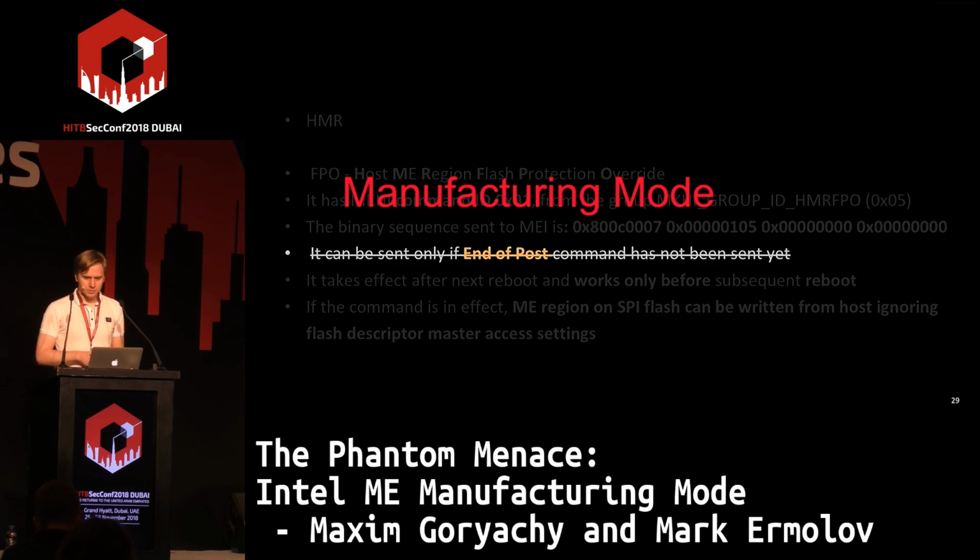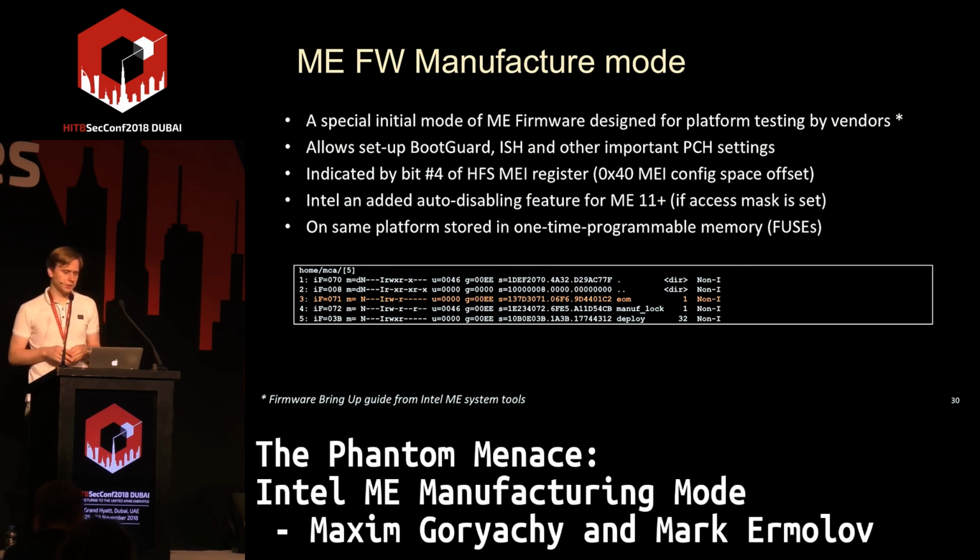So a few words about manufacturing mode. Really, Intel ME manufacturing mode is intended for configuration and testing of the end platform during manufacturing, and as such should be disabled or closed before sale and shipment to the user. However, this mode and its potential risks are not described anywhere in Intel's public documentation.